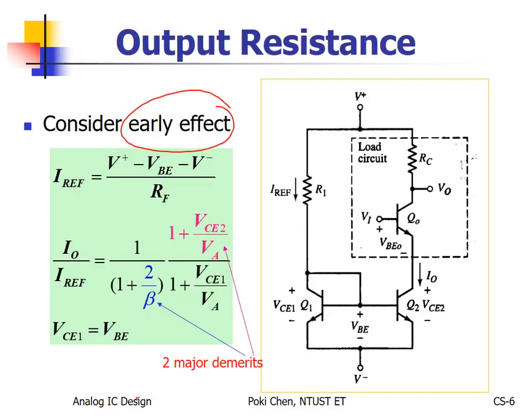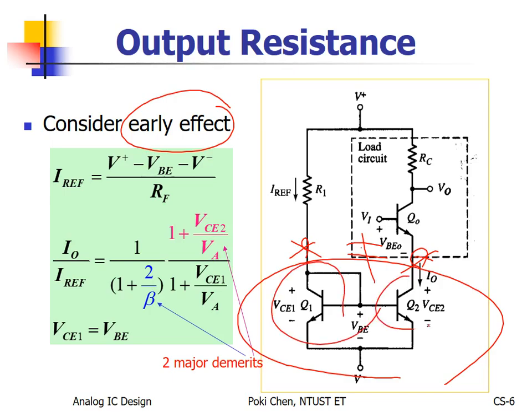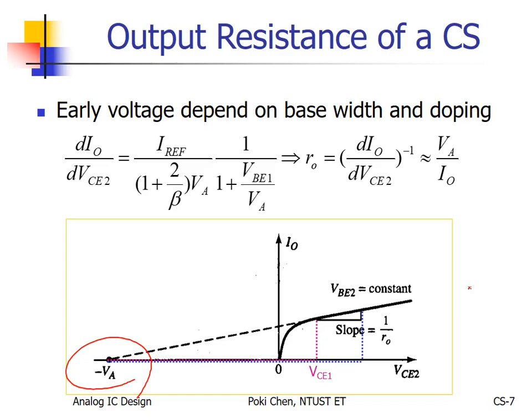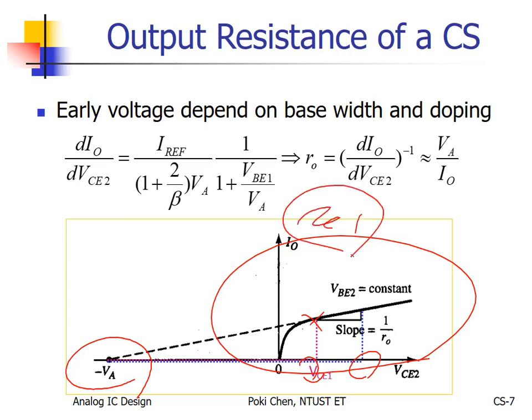Simply because if you look at the structure, this is the input, that is the output, right? So if the voltage here and there are not equal, which is usually the case, sorry for that, even though Q1 and Q2 are exactly the same and have the same characteristic curves, if VC1 and VC2 are not the same, then your current here for IREF, even for IC1, and for the next one, their currents won't be equivalent, okay? That is a very sad idea.